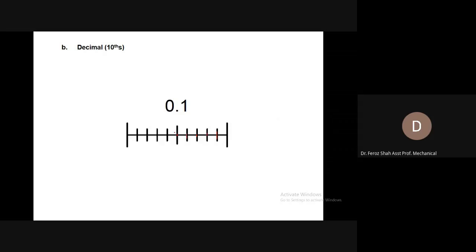But if the fifth division is surpassing this division, it means you have opened the compass a little bit more. So for the next trial, close the compass so that you end up exactly at this division, and the fifth division exactly ends at this point. This is how the hit and trial method is carried out. That is why it is called hit and trial.